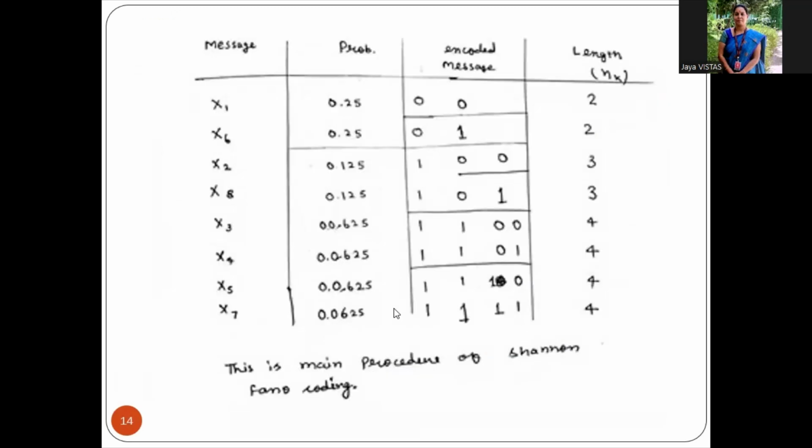Then the next example, x1 up to here, totally we have 8 symbols. The same process is repeated. The probabilities are arranged in decreasing order. Then we separate these into two groups, so that the total probability of each group is nearly equal. Then assign the uppermost group 0 and the lower one 1. The same step is repeated until only two symbols are left.